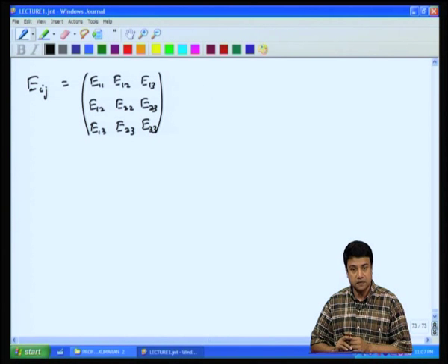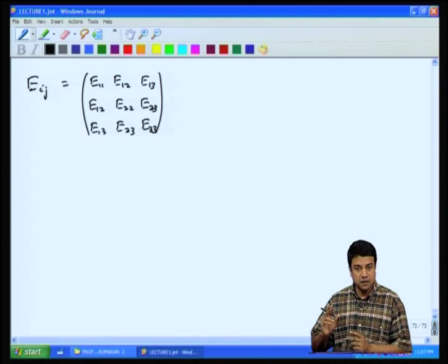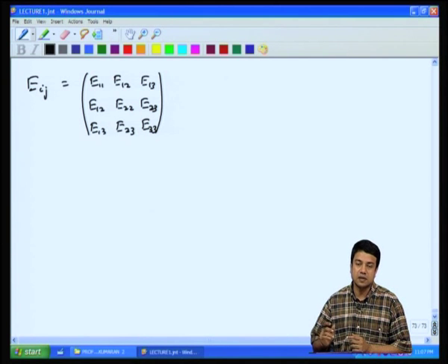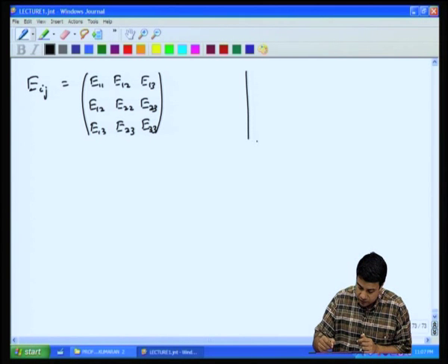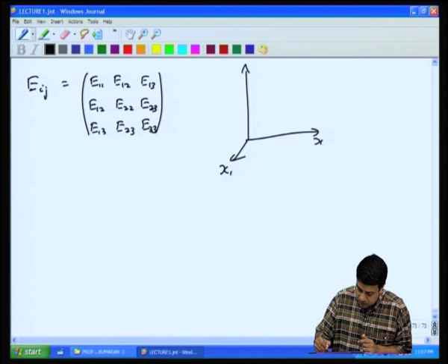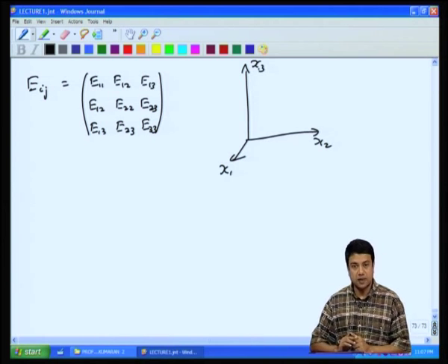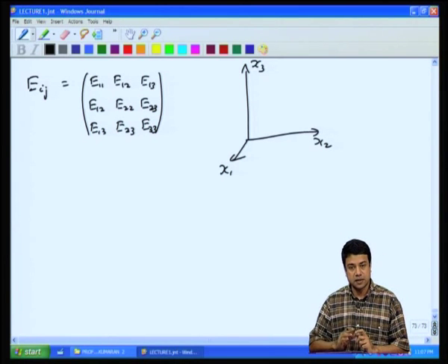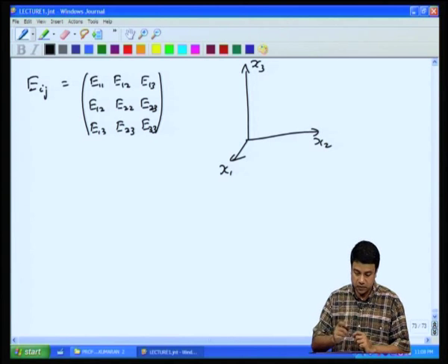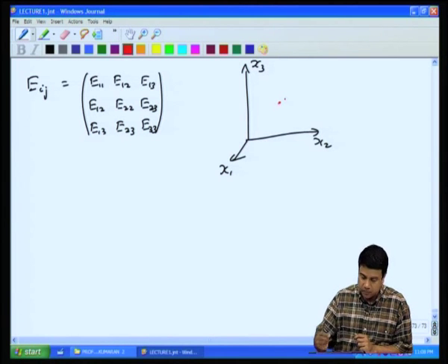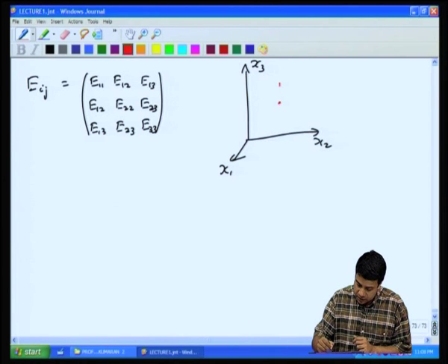So, the eigenvalues of this tensor basically represent the rate at which there is stretching or compression along the principal directions. The eigenvectors represent the 3 principal directions along which there is deformation. For example, in a flow field, the eigenvectors of this symmetric matrix at each and every point in space are all orthogonal to each other. That means that at one particular point in space, I have 3.